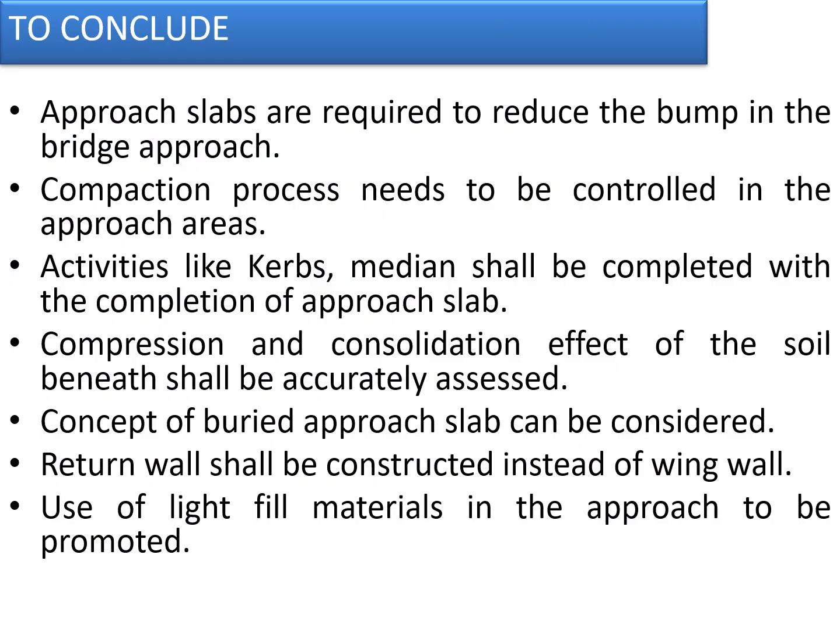So to conclude, approach slabs are required to reduce the bump in the bridge approaches. The compaction process needs to be controlled in the approach areas. Activities like curbs, medians shall be completed with the completion of the approach slab. Compressions and consolidation effects of the soil beneath shall be accurately assessed and taken care of.